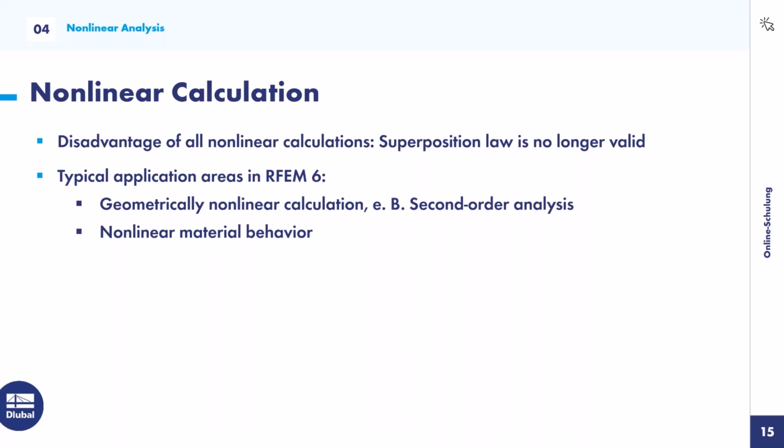Now you also take another load case, a live load case, where you have the material at 100 Newton per square millimeter. If you would superpose them, you would have 335 Newton per square millimeter. The material can't do it. So it's a wrong calculation. That's just one example why superposition mustn't be used for this.